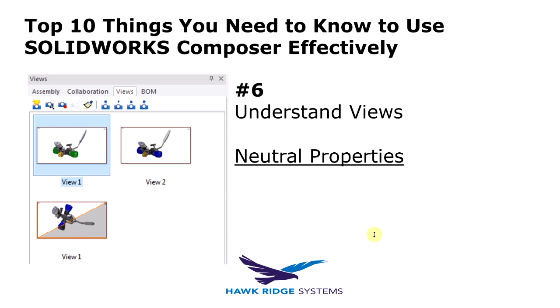So, and I hope I understand this question correctly, but let me go ahead and explain this, and if I don't answer your question, let me know, but I'll try to. So isolating the Composer document separate from the SOLIDWORKS file. When you import anything into Composer, it's not linking to that SOLIDWORKS model anymore until you tell it to. So if I take this assembly and import it into Composer, I can do anything I want to it in Composer and make those changes.